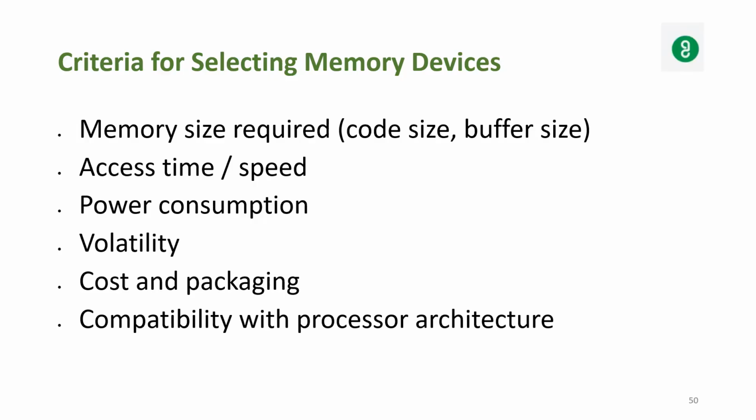Power consumption: if it is a product that you are going to design using an embedded system, you have to calculate how much power it consumes. Based on that, you will decide whether to use a battery or direct power. You have to calculate that before releasing the product.